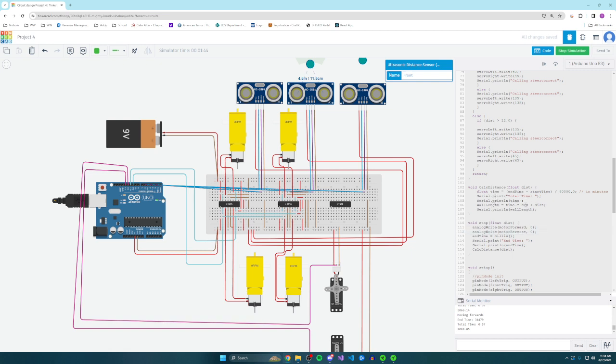Wall length is time times distance per minute, which is calculated, hard-coded to be based on the circumference of the wheel times the RPMs. And then we add in the distance that we are away from the wall based on the echolocator. And that gives us our final wall length, which is then printed.